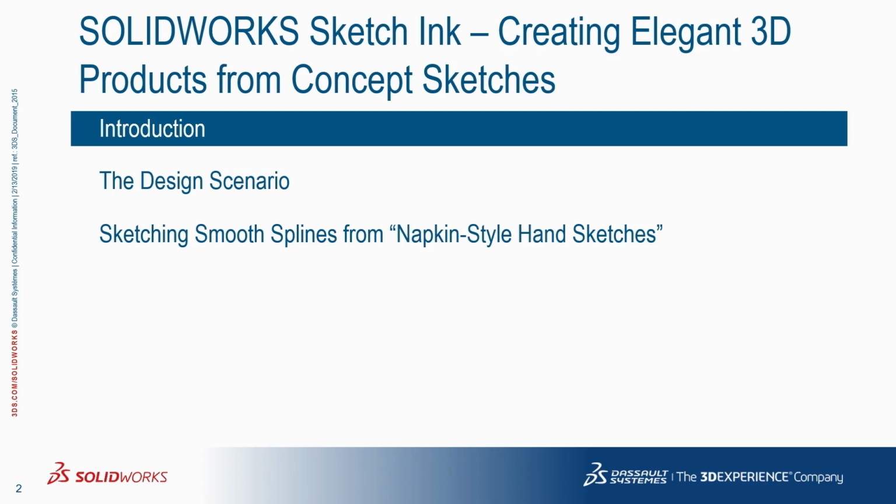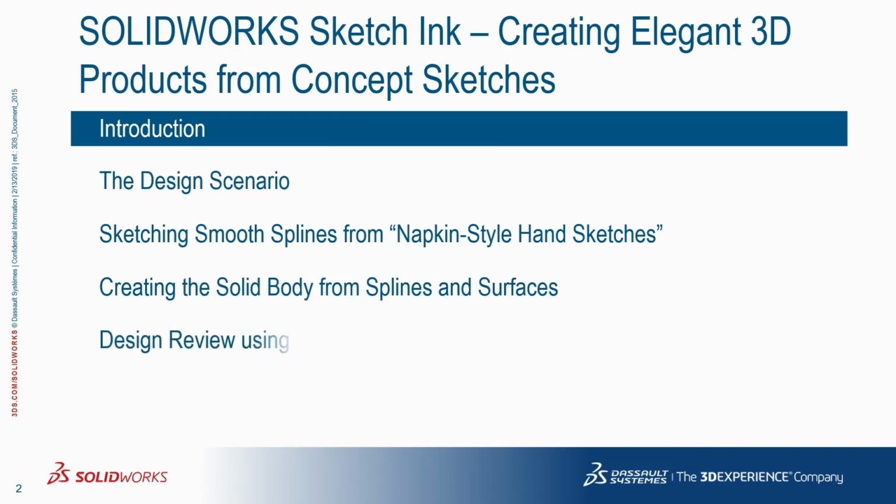So once I tell you about the design scenario, we're going to dive into SOLIDWORKS from there. And we're going to start by focusing on sketching smooth splines using the pen tool on screen from some napkin-style hand sketches, which, if you're ever doing a concept phase in a design, you're going to start with some hand drawings and just get a rough idea of what you're even going for. So we're going to use those, and we're going to draw on top of them and start making our 3D model. Once we start using those hand sketches and creating splines, we're going to create surfaces and a solid body from those splines and start making our 3D model.